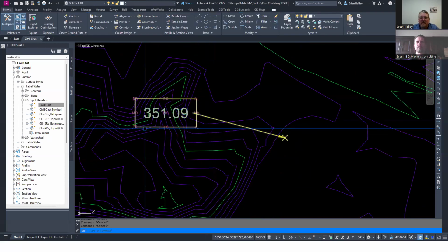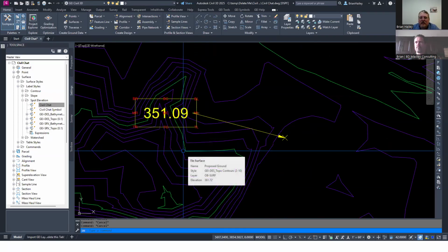So what I typically recommend is if you have a label style that you need to be as composed, and you need to drag it left and drag it right, then I would make two different label styles. Just make a child style that's set up to look good on the left side. So hopefully that helps with that answer.